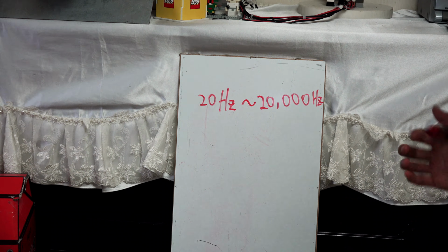And second is how it really works in this ultrasonic sensor. If we trigger this, then when it stops, it sends 8 cycles, like go down, go down, with 40,000 hertz, and it goes through the air.